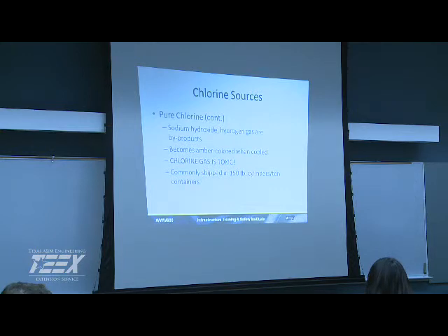In fact, in San Antonio, they have a historic pumping station right there on the Riverwalk, which is a big tourist attraction. It sits below most of the other street levels, so it's a low-lying area. Chlorine gas is heavier than air, so it's going to settle into your low areas. And they had ton containers there. They recognized that was a real potential hazard in that area: a lot of tourists, a low-lying area, lots of chlorine gas, not a great combination. So they went to on-site generation.